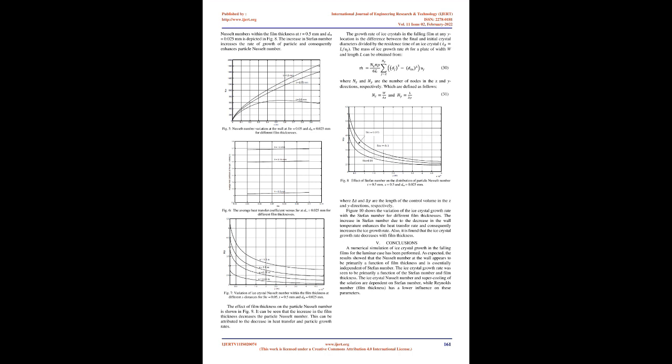As expected, the film temperature decreases in the flow direction and approaches the plate temperature at the end of the computational domain. The reduction of the film temperature is mainly attributed to the fact that during the solidification process, the thermal energy is transferred to the plate surface in the form of latent and sensible heats. During this process, the ice crystals increase in size due to mass transfer from the solution to the surface of the ice particles, leaving behind a more concentrated solution that depresses the freezing temperature of the solution.